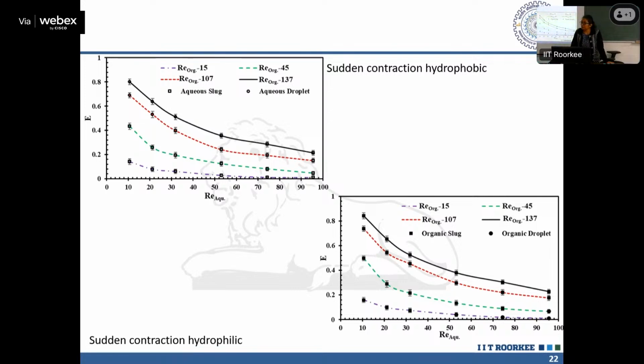One last question. Mass transfer here occurs from the organic phase to the water phase. And we observed that for water there was no wavy structure because of higher viscosity compared to toluene. Yes. So despite the fact that wavy nature was not there, the mass transfer still increased only when it was there in the organic phase.